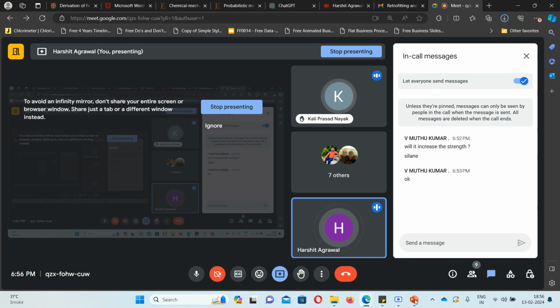Just to say right now, if the reinforcement is severely corroded, you are seeing the tensile strength has been affected. Generally, what is done? Additional reinforcement is provided. That can be done. And now, since the strength has been affected, what can you do? You can think about retrofitting also. If your repair is not sufficient to regain the strength, we can go for some retrofitting also. But how to choose that, we will see in the discussion ahead.